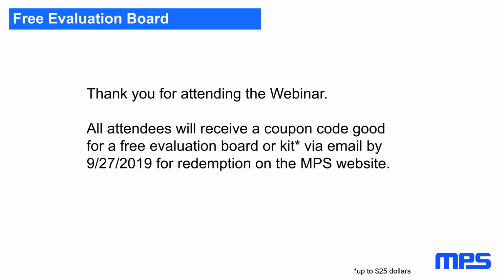Okay, now if I have to cut the noisy ground, how far away from the switching loop should I do that? Yeah, since it's magnetic, it's actually an aspect ratio game. The higher your components are, the further apart you have to go. So it's difficult to guess and estimate, but from heights to widths, I would say a 3 to 10 to 1 ratio. So if I have a 2 millimeter high inductor, I should say 4 to 8 millimeters apart with my cut.